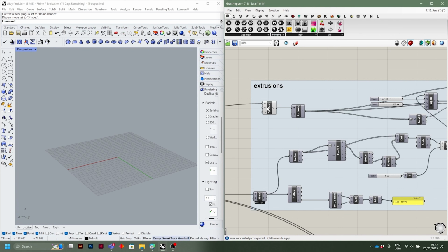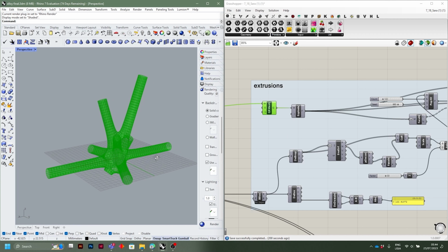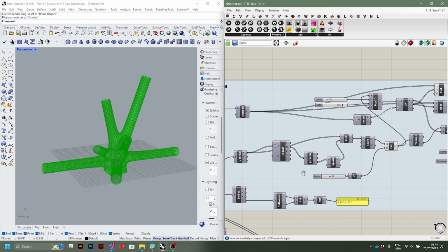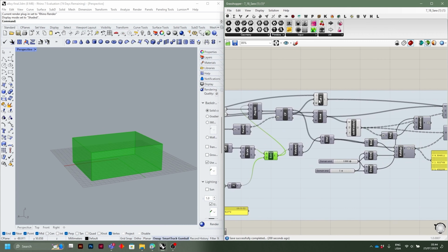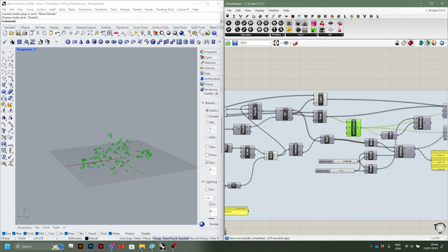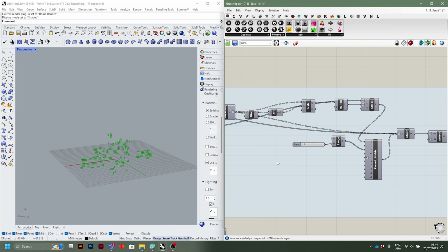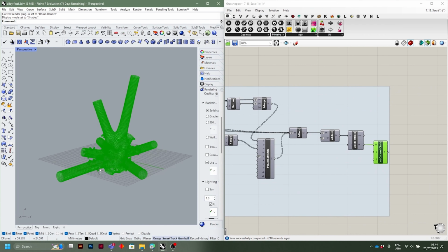And lastly, I wanted to experiment with merging smaller pipes with the original mass. So first I used a quad remesh to make the grid more square-like rather than a rectangle. Then I used the bounding box and culling the spaces where I want each pipe to go, and then used Weaverbird mesh window and Catmull Clark to merge the masses with the pipes.